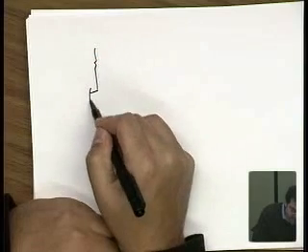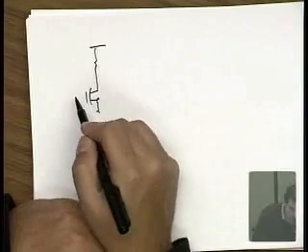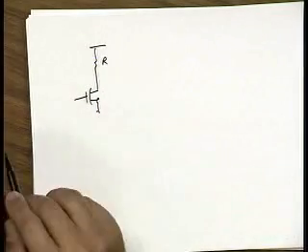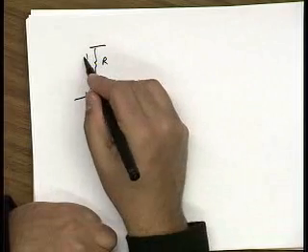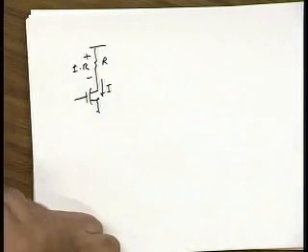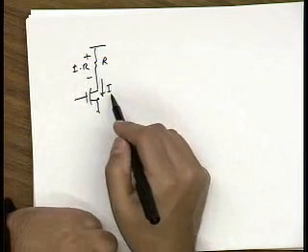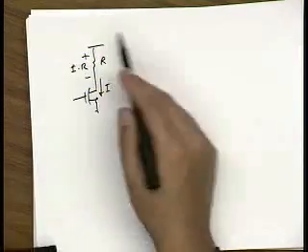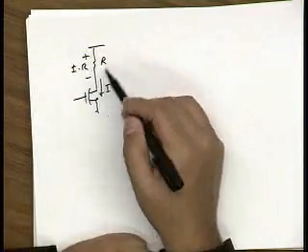Let's say I'm designing an amplifier and I want to get large gain. So I could put a large resistor here, but that's going to consume a voltage headroom of I times R, right? Pretty soon I have to stop. Either I have to stop increasing the current or stop increasing this resistance. And it's going to take a huge layout, right?